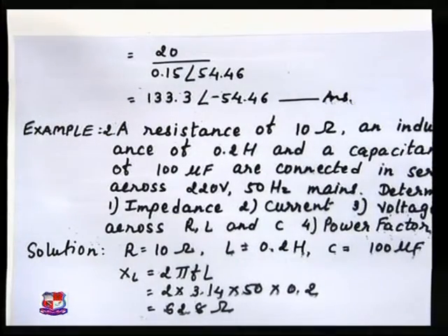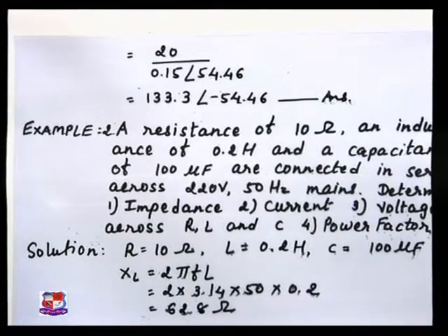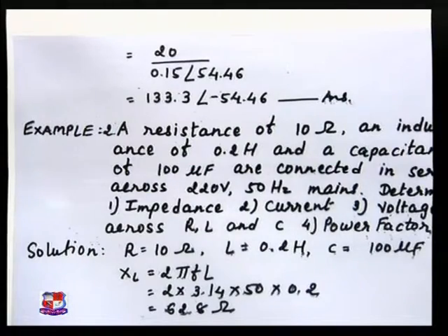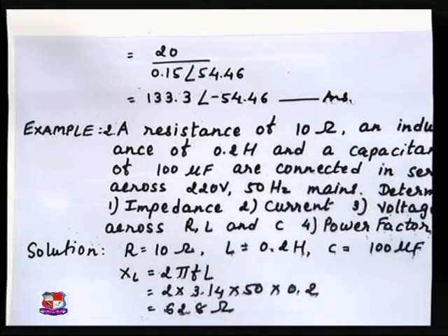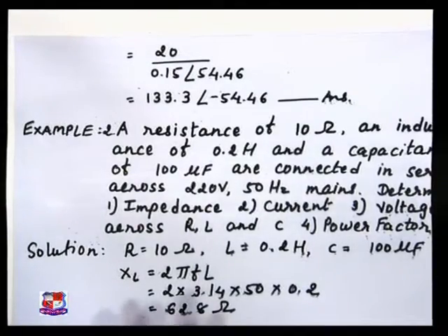Okay. So whenever a parallel circuit is given to you, instead of impedance you have to consider the effect of admittance. So first of all find the admittance for an individual branch, then find the equivalent admittance, and then find the supply voltage. Now second example